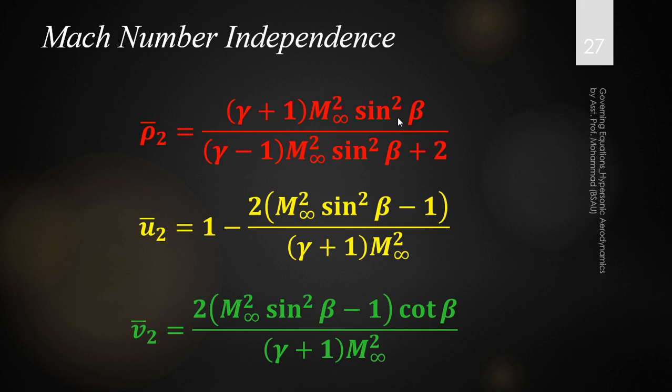So it is already at a higher level, and it reaches the Mach number independence, where the Mach number influence becomes ineffective for the phenomena and for the Cp calculation, sooner than the cone and cylinder combination. So a sphere becomes independent of Mach number sooner than the cone cylinder, because M square sin square beta is higher for the sphere.